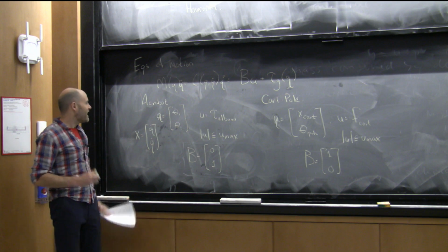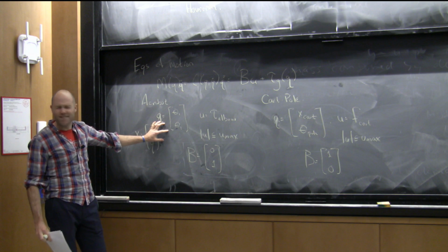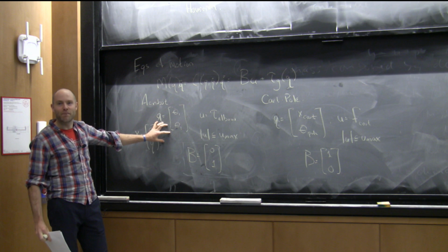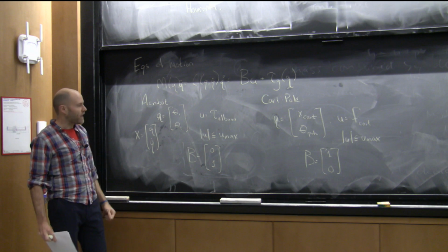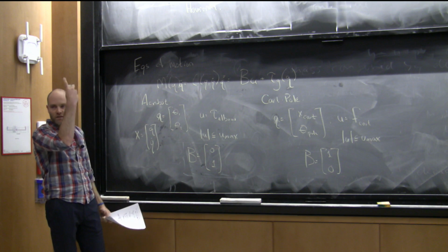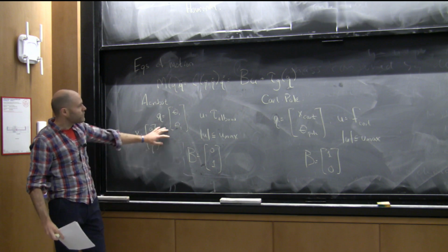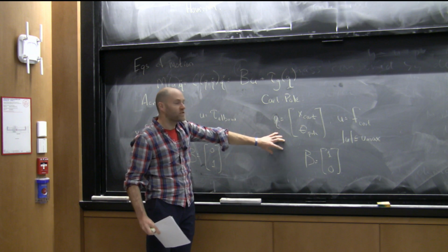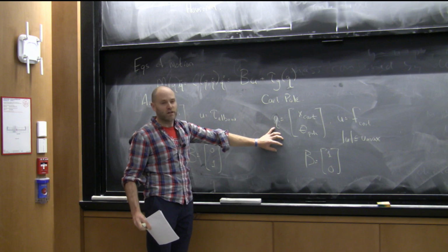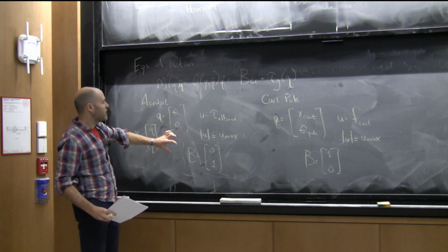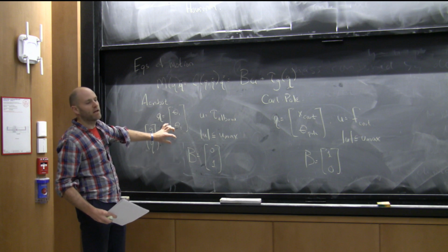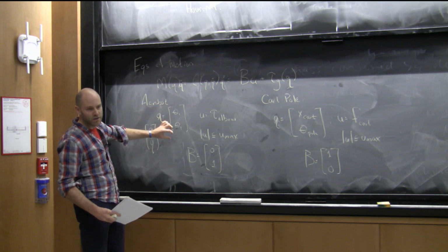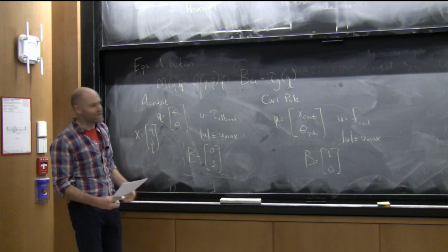But at some point, this doesn't feel like the right solution to the problem. There's got to be something better once you get to the top. It is really a hard balancing problem to stabilize at the top. On the cart pole, I think it's the same experience, but you might need more resolution than you expect, though I think this works better, and we've seen that work better. People have accomplished swing up of the Acrobot with value iteration on a mesh. It is possible. I've never had the patience.